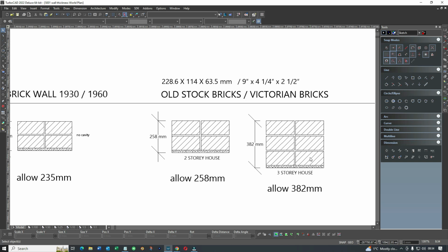And it's hard to get your head around that. You think, oh, I've made a mistake on the numbers, I got this wrong, so do I go with the top, do I go with the ground? Anyway, when you find yourself in this situation, just consider that, was it a 2-story, 3-story or 4-story, because of the wall thicknesses. In fact, if it had a basement when you go down, it could well be 4 brick thickness. So you have to check that out and look at the building, not just throw walls up.